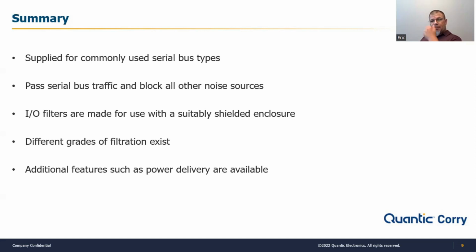As you can well imagine, the I/O filters aren't much use without a shielded enclosure of some type, because without a shielded enclosure, the noise would just transfer from one side of the filter to the other. So that is a necessary part of the equation.